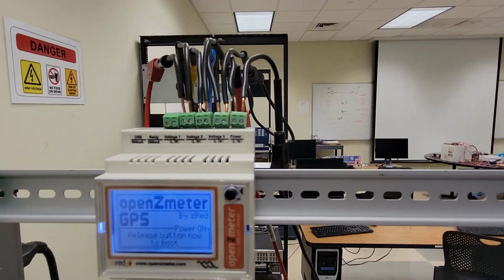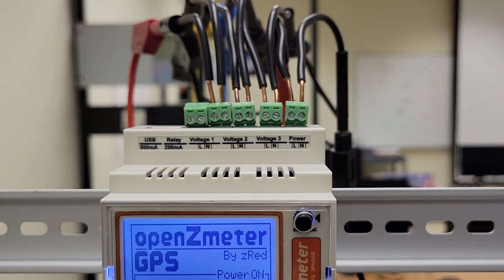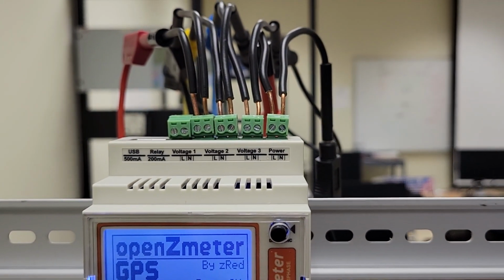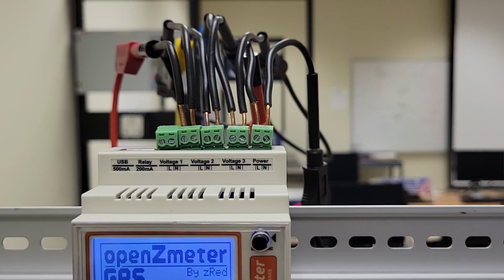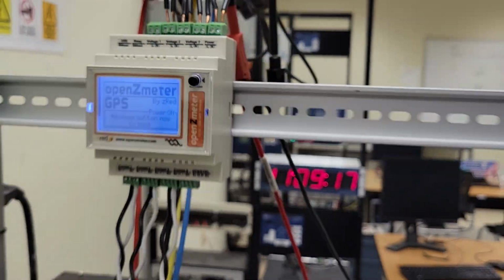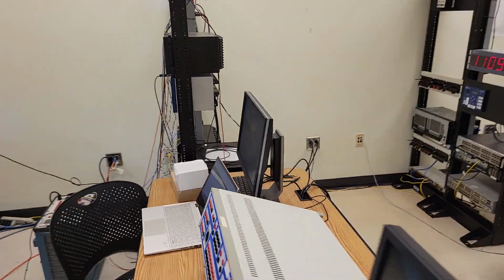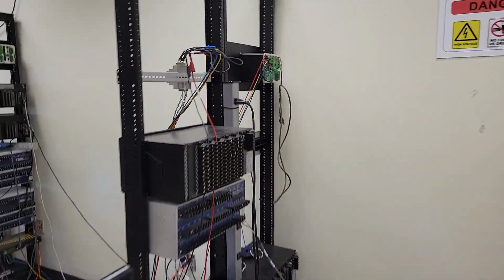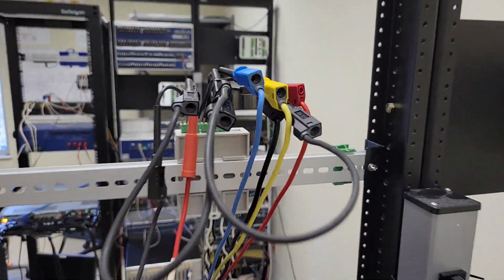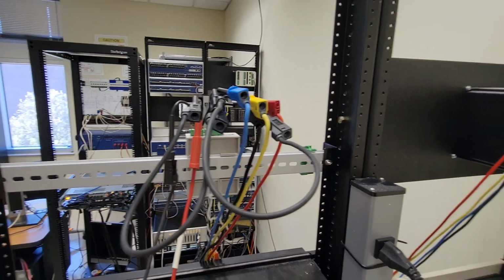into the meter. And you'll see the lines from left to right, A phase, B phase, and C phase, and then next to them is the neutral, which is tied on the back. And I'll go over here real quick. The neutrals are tied for that Y connection.